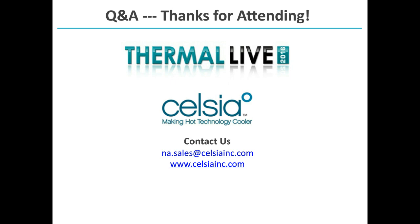Whereas my vapor chamber is a flat device. Flat vessels are terrible pressure vessels. So as I get to, say, 105, 110, or 120 degrees C, that internal vapor pressure is going to want to make that nice flat vapor chamber turn back to round. What we do is we design a fixture that holds the vapor chamber flat during the soldering process. And we have a little technical paper on how to do that. So we can also offer that to anybody who wants it.